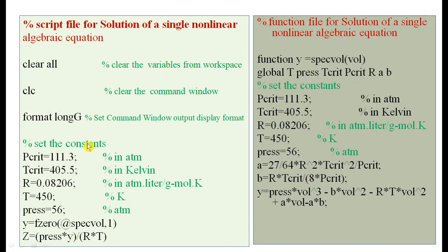Then after that we start our program. First of all we write the constants: critical pressure, critical temperature, ideal gas law constant, and the temperature and pressure already mentioned. Then we solve this f(V) by using the function y = fzero(@specvol, 1).